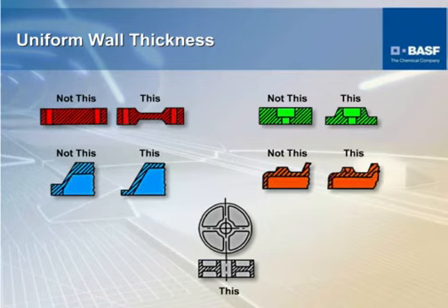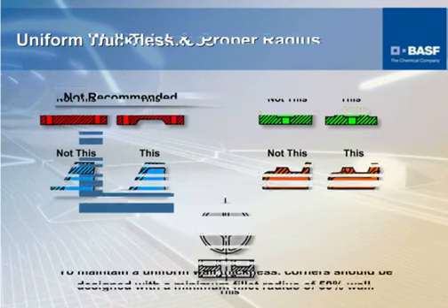And you can see here, if this was your original design in, say, metal, with plastic, you'd look at it and you'd say, okay, let's core this out. And now overall, my wall thickness there, and now in the center are all about the same. So that would be a good design. Following that principle really is helpful, as any of you probably know if you've been involved designing with plastic.